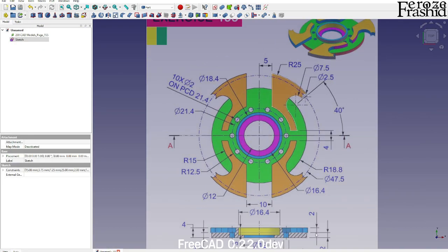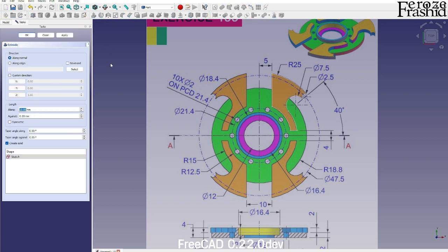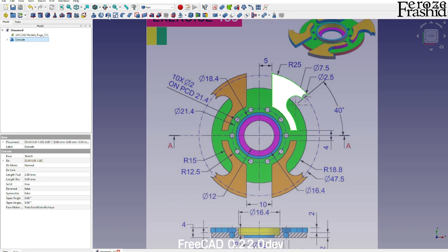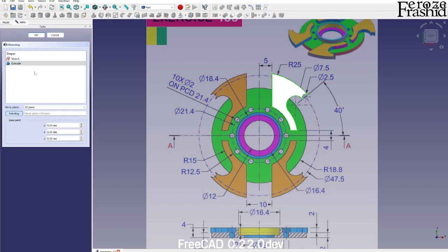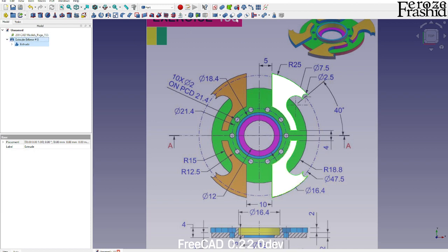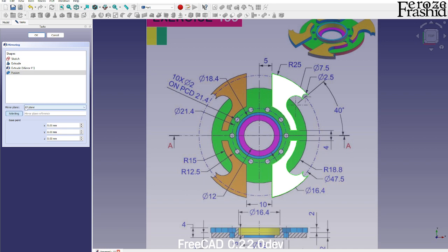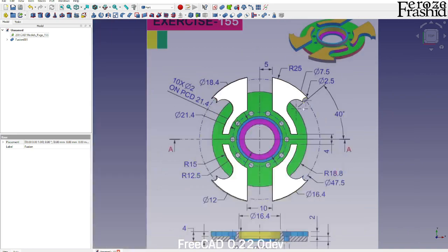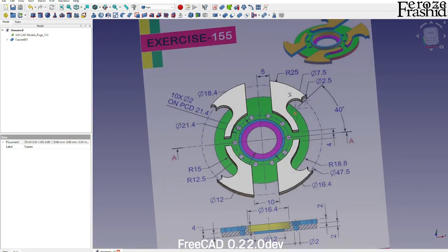Go ahead and do 2 millimeters of extrusion. There, we got it, and I'm gonna go ahead and mirror it over on the XZ plane. Then make these two one fusion. Obviously, after that, I will be doing the YZ plane. So we got the 4 wings of this object done.